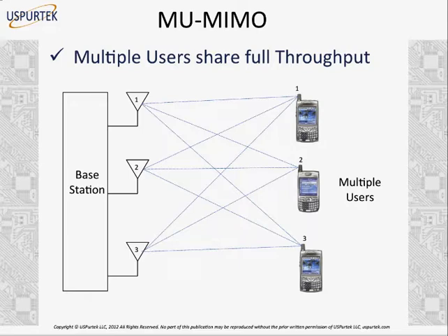So in this case, the present deployment of LTE that is happening currently in North America, in Asia and other places, is actually multi-user MIMO, where the base station has so many antennas, I mean 4, 5, 6, because on a cell tower you can put many more antennas. But the user phones have single antennas, and all of them share the bandwidth. But as an end result, they get more bandwidth than they had before. Before, the base station had a single antenna, transmitting signals in one direction. Now the base station has multiple antennas. Multiple antennas means it can deliver more bandwidth to each user, even though it has a single-antenna phone.